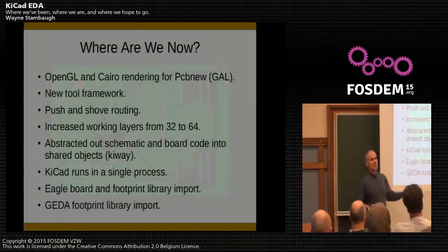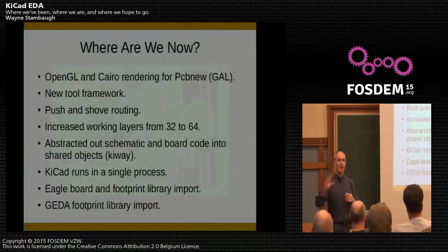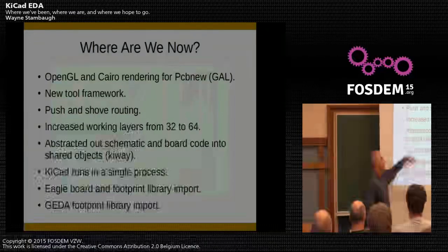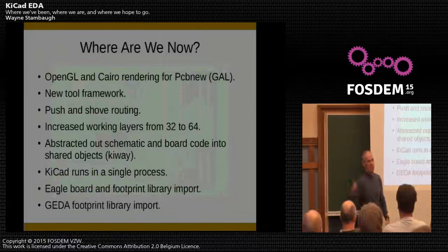Running a single process is now going to allow us in the future to do back and forth between the board editor. So say in the case of pin swapping or part swapping, I'm laying the board, oh, I got a cross node. Well, if I just swap those pins, my cross goes away. So we will be able to do both forward and backwards annotation between both. And that's way future, so don't ask yet.